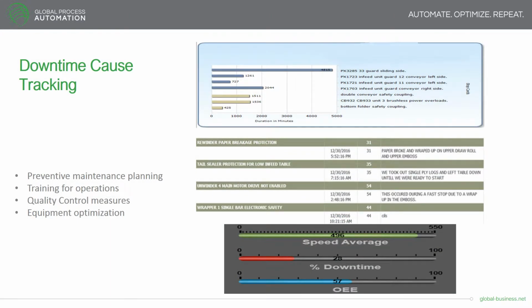Downtime tracking can be used in preventative maintenance planning. By capturing any time that the machine is in a non-running state, we're able to quantify this by duration and type of outage. Showing a Pareto chart over, say, the last 30 days, we can easily see where habitual bottlenecks and stops occur.